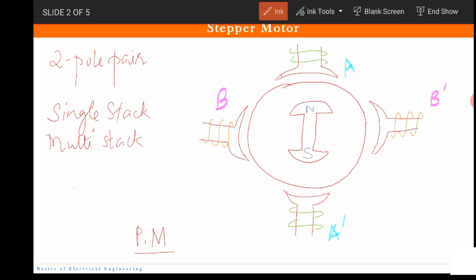Fine. So what we are going to do is, first we will energize pole B. So the current starts flowing in B. Here it flows in the opposite direction. So now because of this current, this pole becomes a north pole and this pole becomes south pole. So this becomes south pole and this becomes north pole.